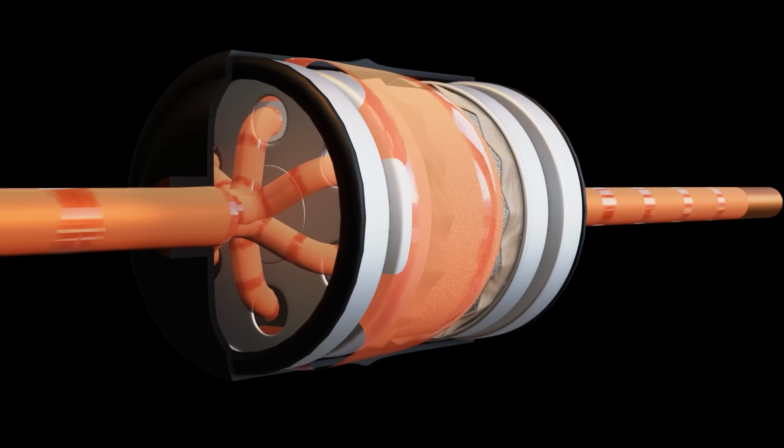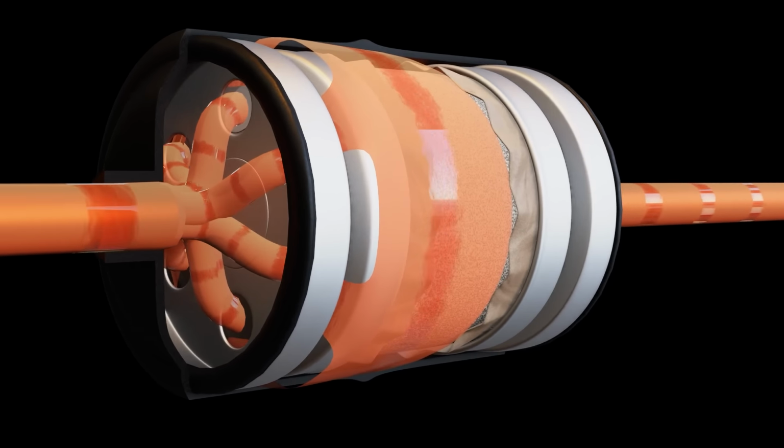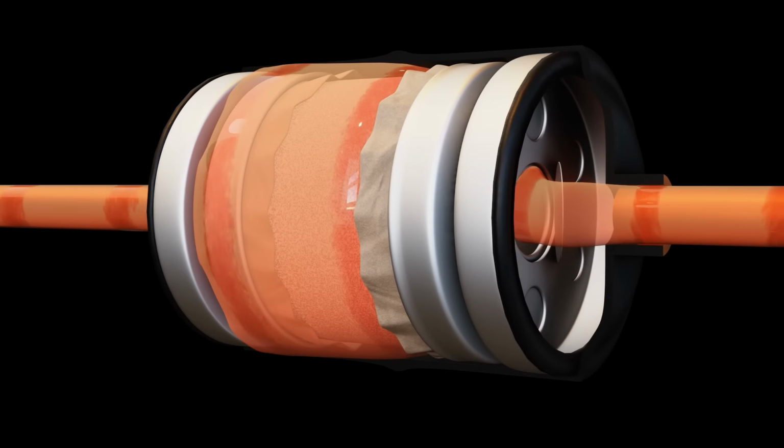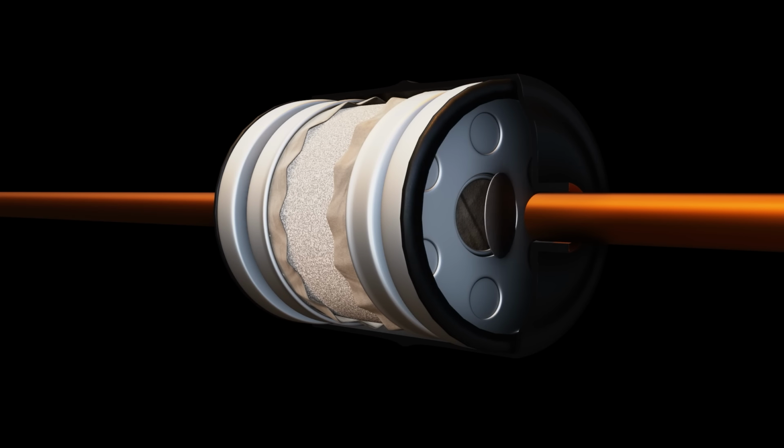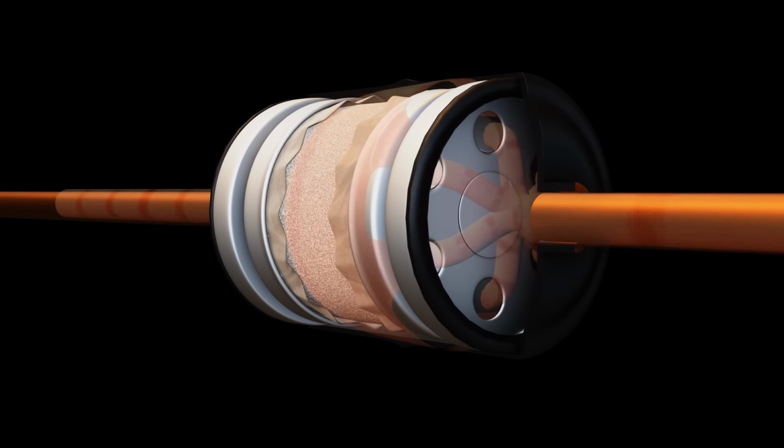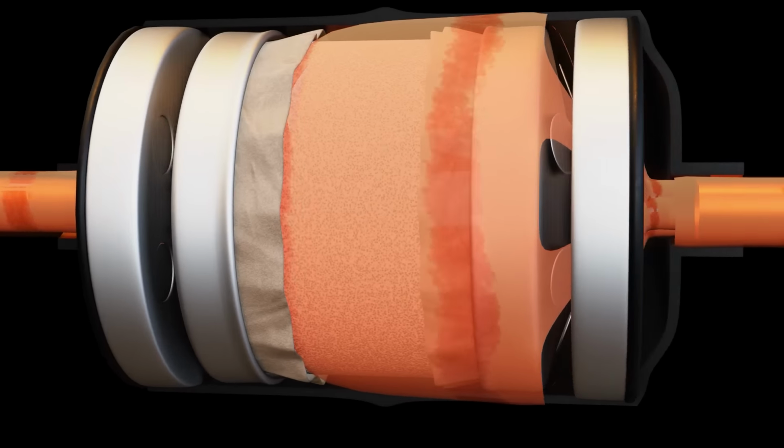But you can see with this check design, it can work in both directions. So if the flow is going in heat mode direction, it will work, and as well as if it goes the other direction via check valves on both sides of that biflow dryer, whereas a single flow dryer, or a one-directional dryer, only works in one direction.